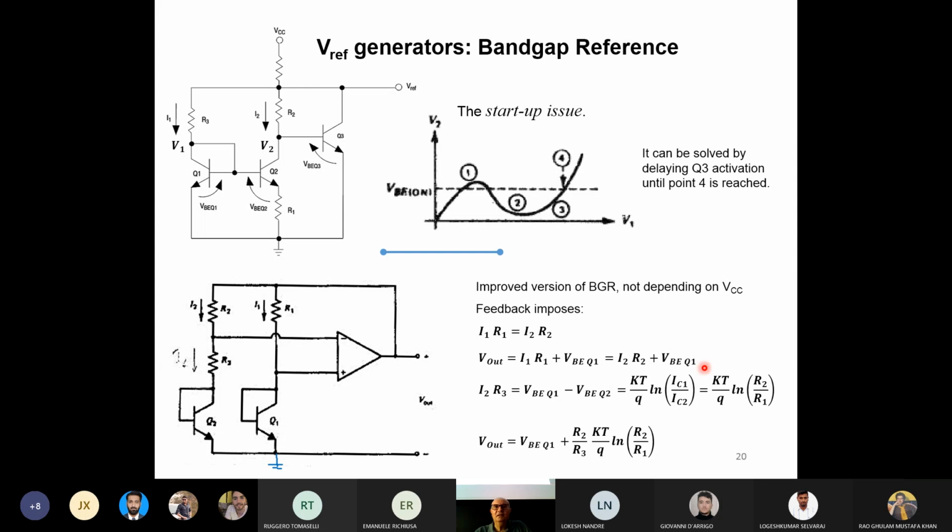Yes, the supply is connected to the op-amp. There we can write, there will be two wires. One is VCC, only going to the op-amp, yes. The other voltage could be even ground. It is not necessary that we have a negative voltage. Just because all the output voltages are positive, we can also use a good op-amp with the ground here. Okay, no problem. It should work right the same.